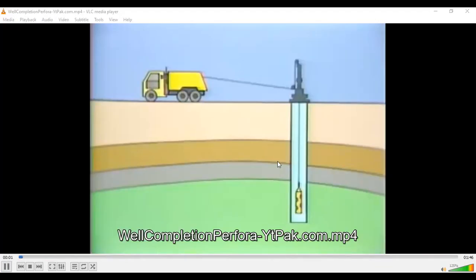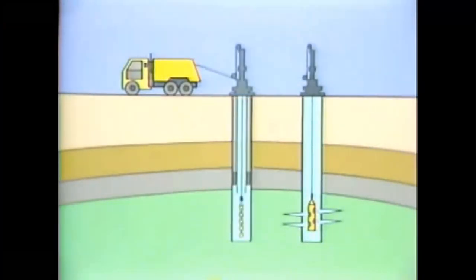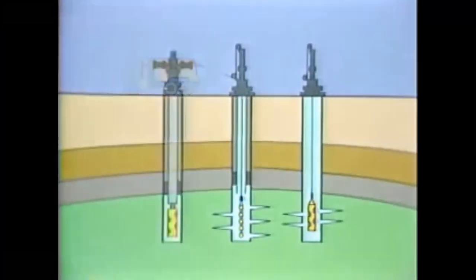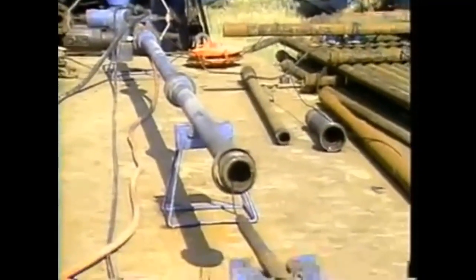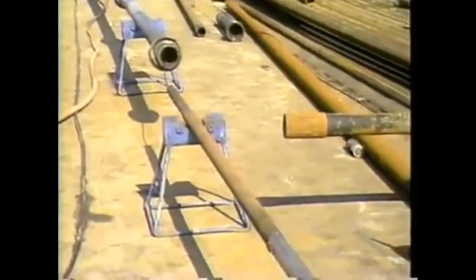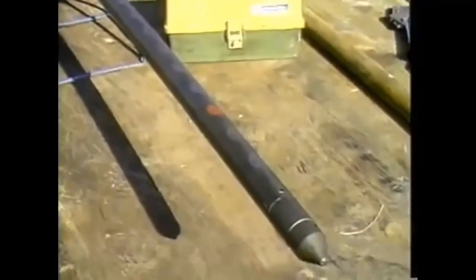Cased holes may be perforated in several ways. This perforation is the job of the production engineer. Conventional casing guns run into the well on electric wireline through wireline pressure control equipment. Using through tubing guns run into the well after the tubing has been installed. Or using tubing conveyed perforating guns run on the bottom of the tubing string and detonated using mechanical, electrical, or pressure-activated firing mechanisms. Also, the delivery system for placing the shaped charges at the proper location via wireline may be categorized as one of 3 possible types.